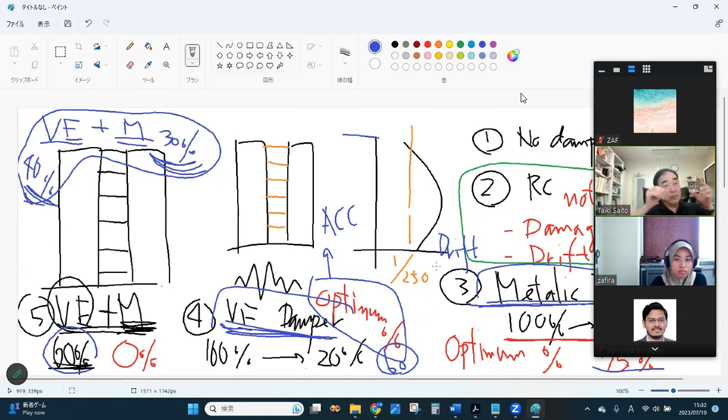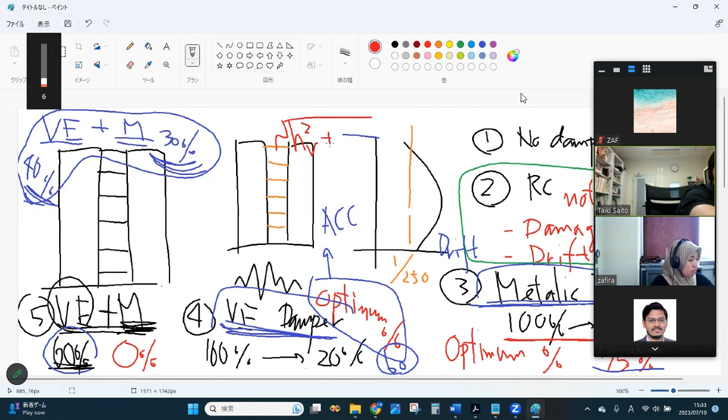I mean, without using time history, we have our design spectrum, and we must calculate equivalent damping for viscoelastic material, equivalent damping for metallic damper, and if you combine two dampers, you add two equivalent damping factor, or previously we proposed to have a damper of viscoelastic squared, damper of hysteresis metallic damper squared, and taking root.